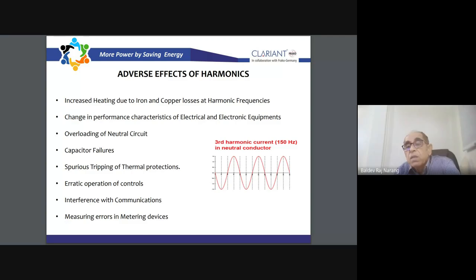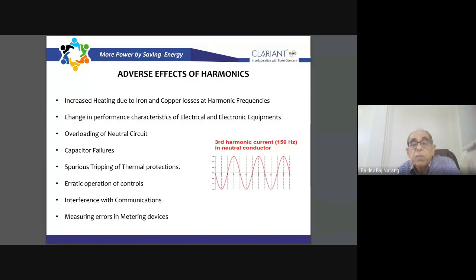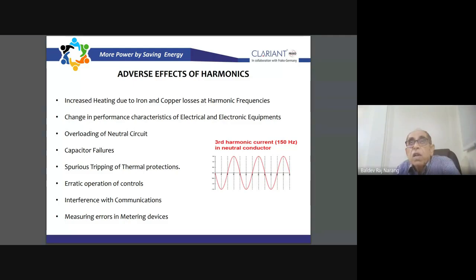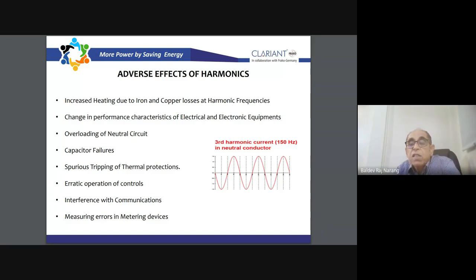Baldev: Yes, sir. Does the unbalancing load also affect the voltage harmonics? Speaker: Which one? Please repeat your question. Baldev: Unbalanced load, phase unbalancing, load unbalancing on the different phases. Speaker: So that is what I was talking about. Whether it is unbalancing due to any reason or due to single phase loads, it is the same thing. It is generating third harmonic, and that is what is affecting the neutral loading also. It is created in the system because of the unbalance only.